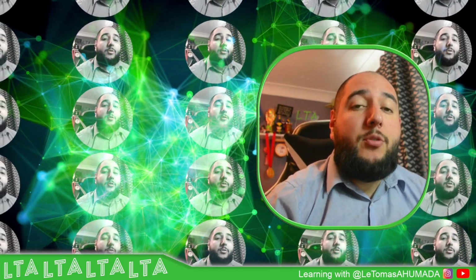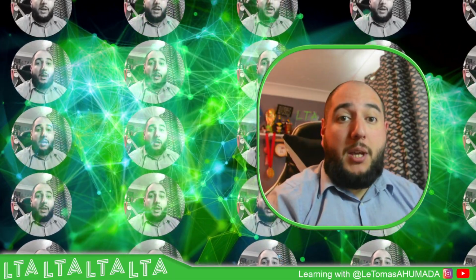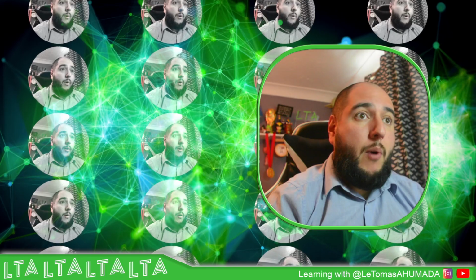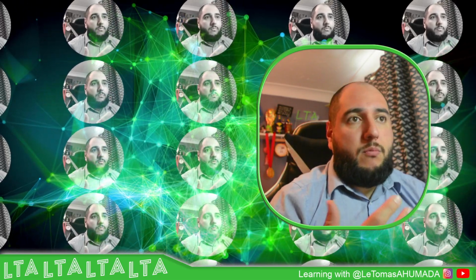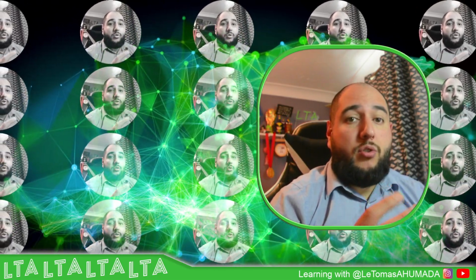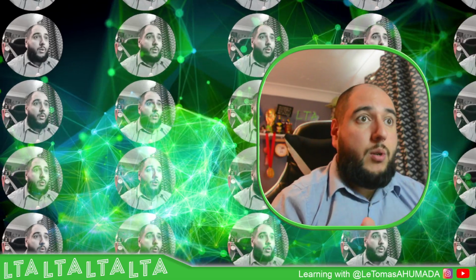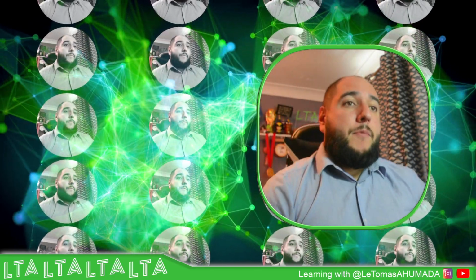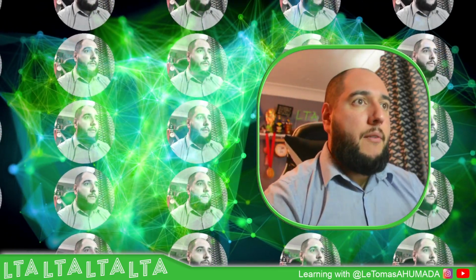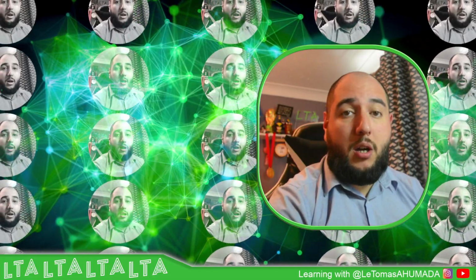I'm your host, Leandro Mada, and in this video we're going to see how we can communicate the M240 using the NOE card with another PLC, which in my case is going to be a Modicon M262 programmed in Machine Expert. In the previous video we saw how to use the read and write bar function blocks in the Modicon M340 using the embedded Ethernet port. That works well, but there are always better ways to improve how we work, especially in coding. Instead of having multiple function blocks, we can use something called IOScanning that the NOE card has.